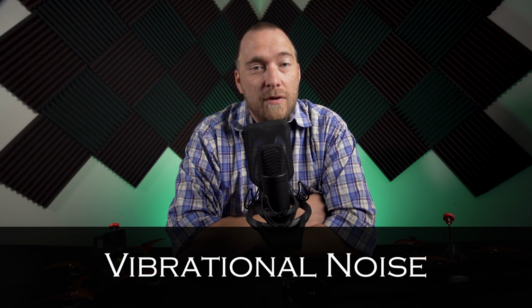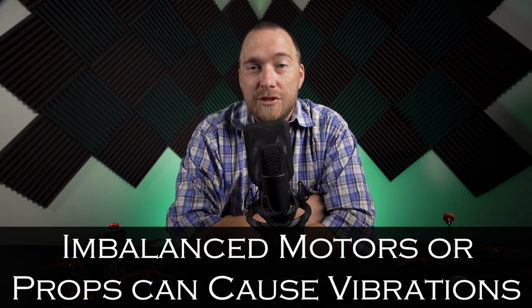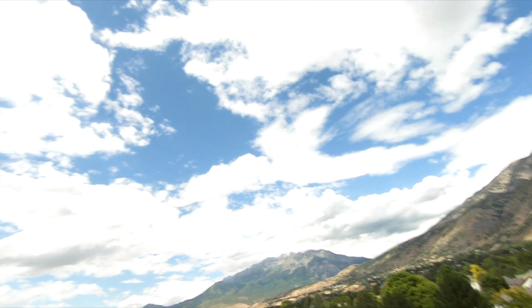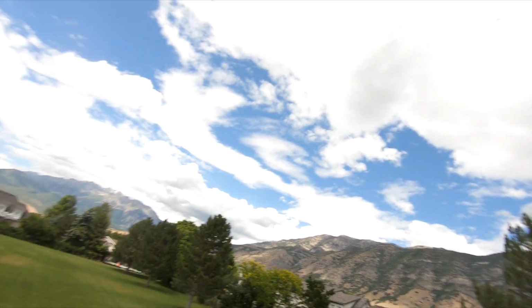On your drone, the kind of noise we're talking about is mainly vibrational. You have a rigid frame with 4 motors spinning props at high speed, constantly changing RPM and wind resistance. All that adds up and creates vibrational noise on the drone. Also, if a motor or prop is not balanced, it will cause vibration that the gyro will pick up, causing it to send noisy data to the PID loop, which will make your drone's maneuvers sloppy. That's where filters come into play.